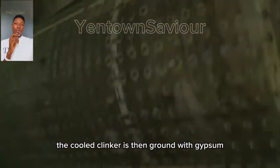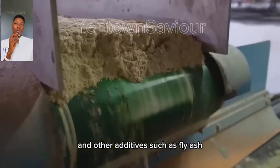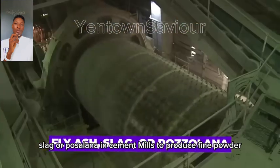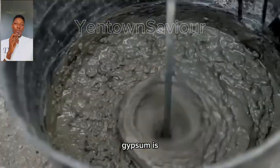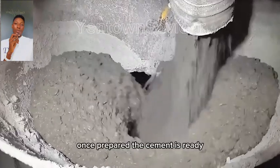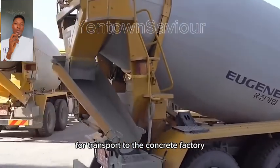The cooled clinker is then ground with gypsum and other additives such as fly ash, slag, or pozzolana in cement mills to produce fine powder. Gypsum is added to control the setting time of the cement. Once prepared, the cement is ready for transport to the concrete factory.